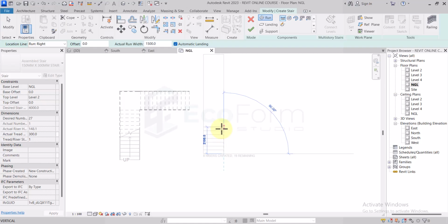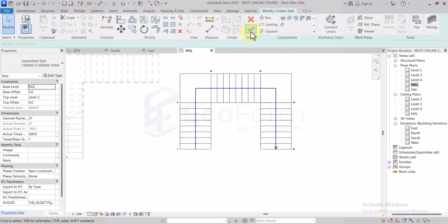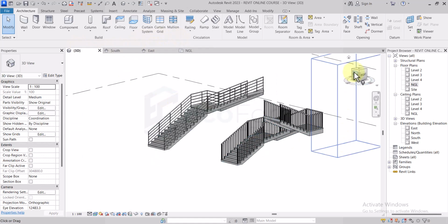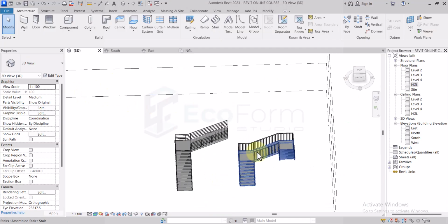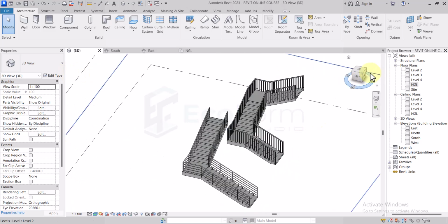Start drawing. You can say, okay, 8 risers created, 19 remaining. Let's do 9. Then come here. Let's do another 9. Then come here. Let's do another 9. So mark that, and like that. So you see, this is another type of stair. You climb, land, then climb. So that's basically how to create stairs.